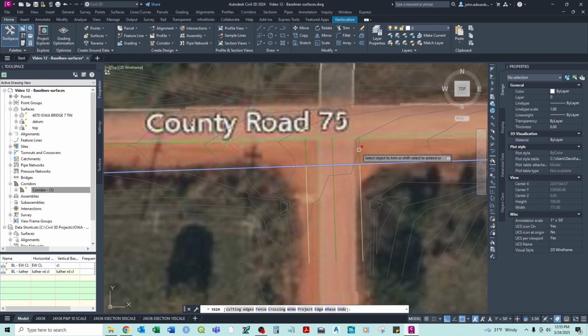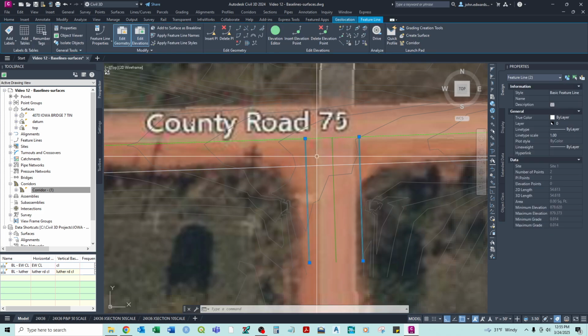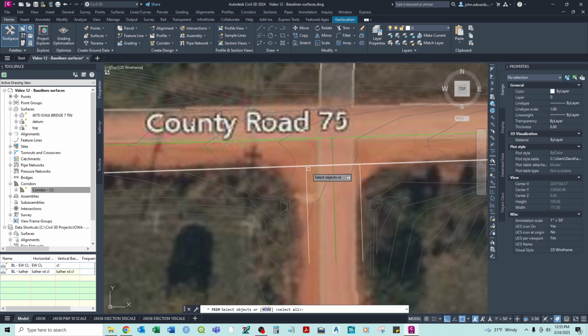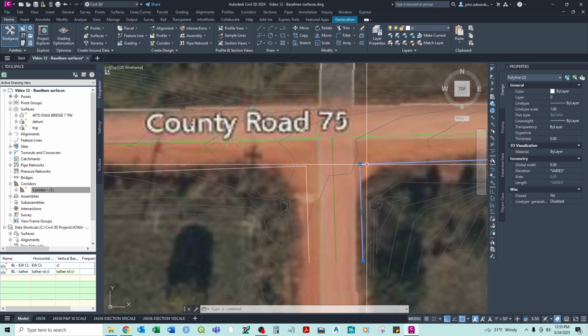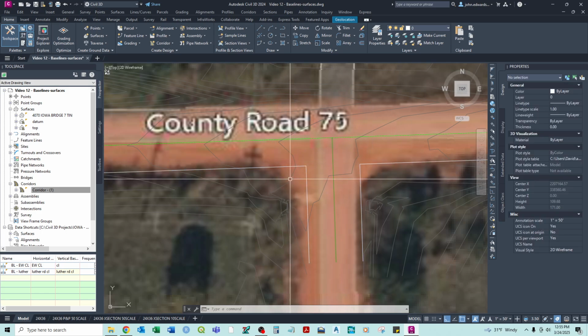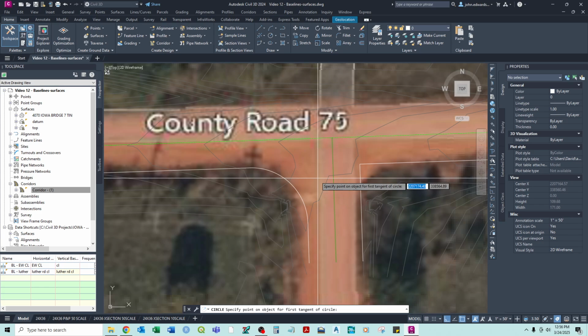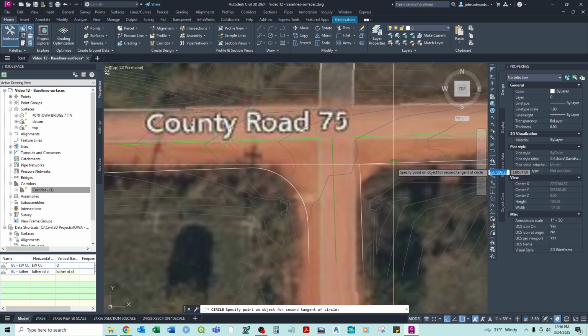One thing, we're just going to trim these up and get rid of these. One thing to note when you're doing this is all of these need to be ideally on the same elevation, or it generally won't work. So if we set all of these, and let's just say the elevation is 100, that's not the final elevation we want, but if they're all the same, then we know they're on the same plane. So we could use fillet. Select the radius as 25. Click here. We could equally do a circle, TTR, tangent. So we click tangent, and specify the radius, which is 25.